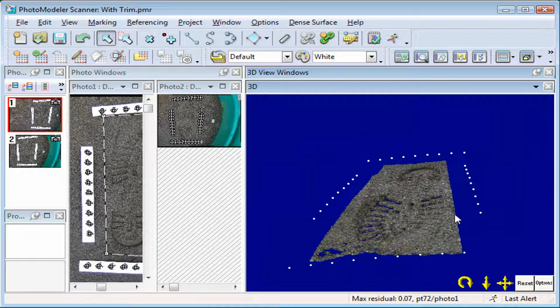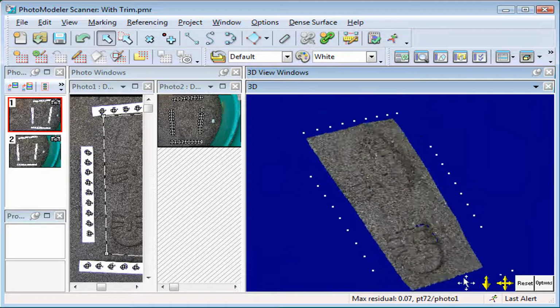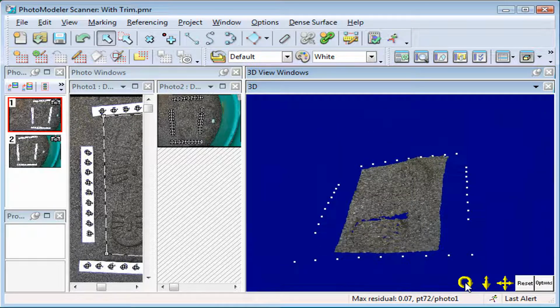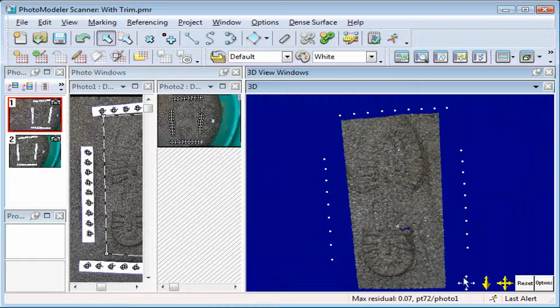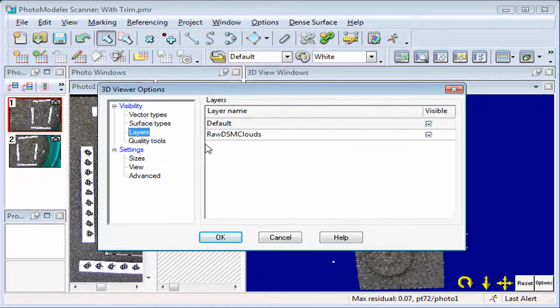Images taken directly from above may provide data for all areas of this particular shape, but another technique is to include more than one set of stereo photos. This is covered in the multi-photo and troubleshooting tutorials. If your end goal is a triangulated mesh, holes like these can be filled in during triangulation, as covered in the triangulation tutorial. The raw point mesh data generated from photos will automatically be added to the raw point mesh layer, so it is easy to hide all non-triangulated point meshes.